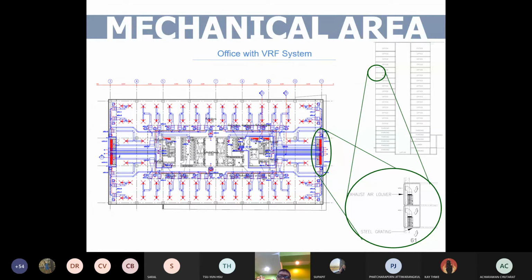So it can substitute the air cooled chiller right away, and they still have the same effect as the air cooled chiller, in that they can share the load. When they share the load, they create the diversity factor. Let's say this side of the building, the fan coil, is on the east. In the morning they have sunrise in this area.